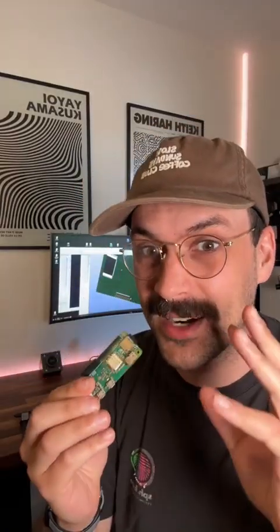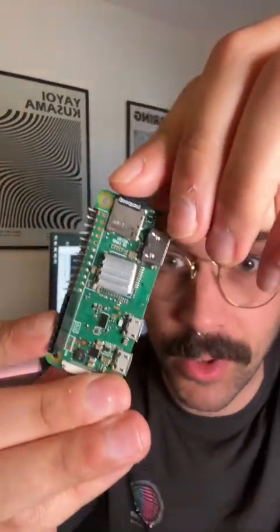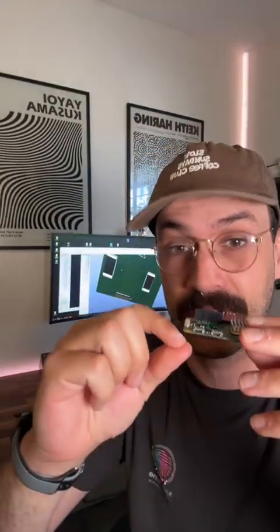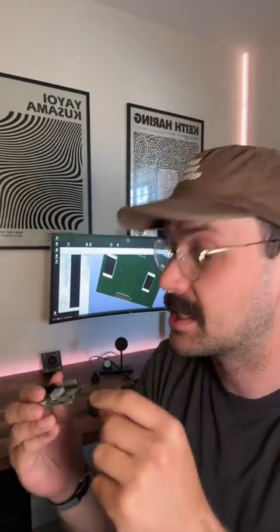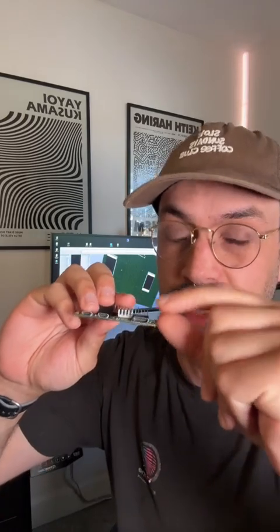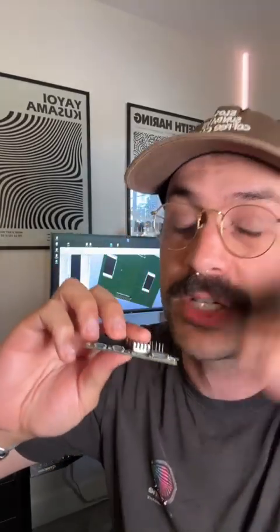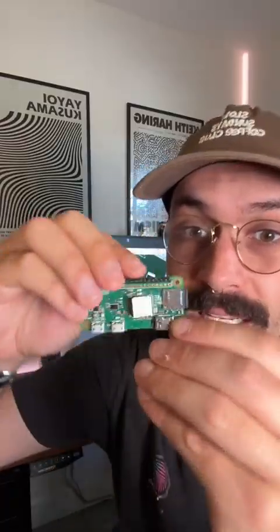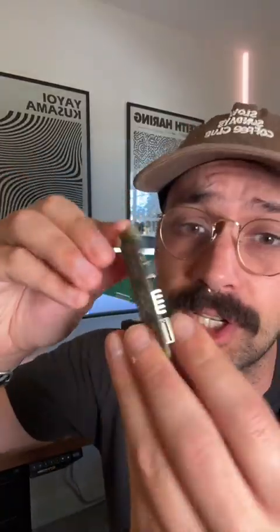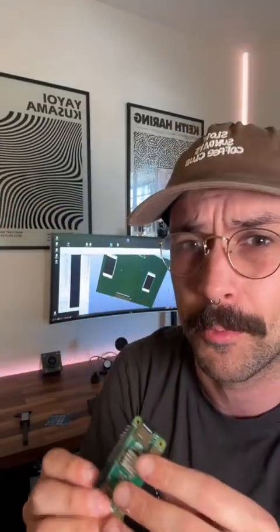Now, when you want to start making super compact boards, take something like a Raspberry Pi here with a ton of components. It doesn't actually stop at just 2 layers. There's PCBs that are 6, 7, 8, 9 layers that are pretty much the same idea of having just the front and the back, but it's a whole bunch of PCBs sandwiched together. That lets you run through a lot of different layers and have a bunch of different levels that you could jump over traces on, which lets you basically make something super compact like this. But that's kind of out of scope of this. For a lot of hobby projects, 2 layers is going to be all you need.